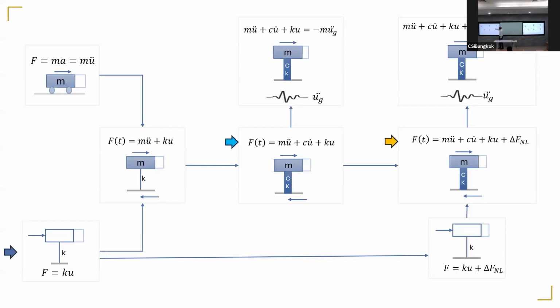It's a time varying force, and then mass, acceleration, damping, and everything, and nonlinearity should come into play. But normally we ignore nonlinearity for wind. We design it for service. We come to this level, and even that is too difficult, so we go to that level. So that's how inaccurate or approximate the wind code analysis really is for structures. We are very far from the true behavior.